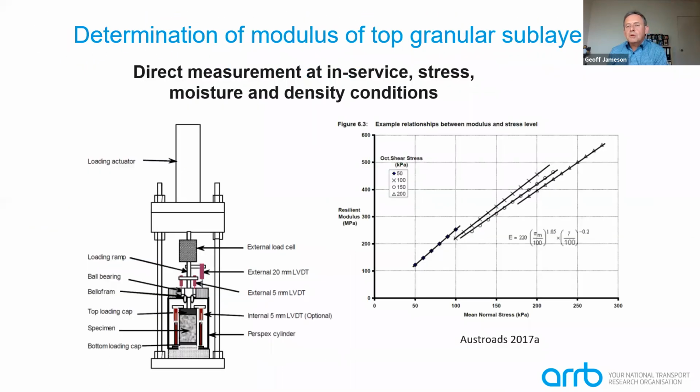So the question was, has the effect of confining stress been considered, in the modulus characterisation? The effect of confining stress, yes, considering the base material is so close to the surface? Well, in our repeat load test, we provide a constant confining stress.